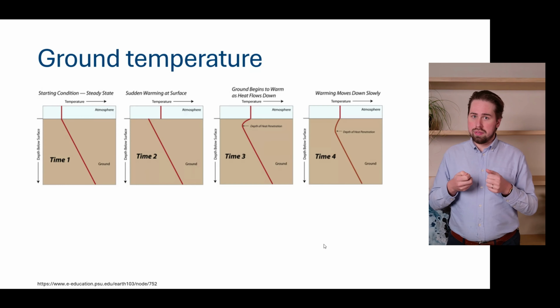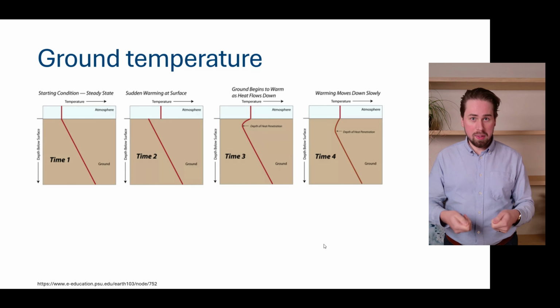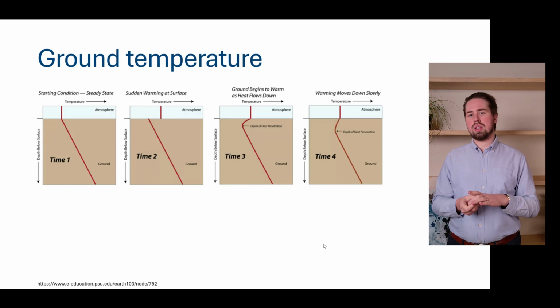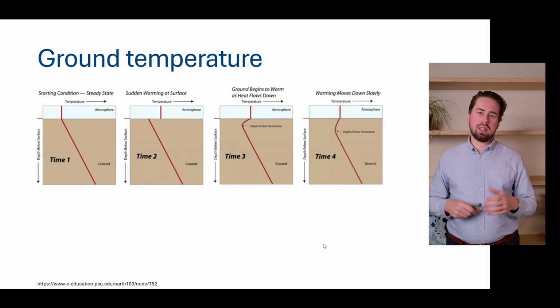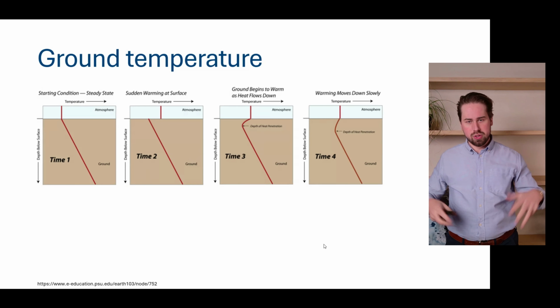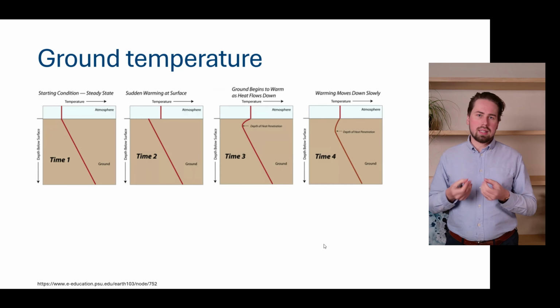So there is, especially in older cities, this problem of this temperature bubble, where if you want to find cooler ground, you actually have to drill deeper to go to this colder ground again. This is important if you have problems with cooling or your building has a high cooling demand, because you want to stay away from this high temperature, so you want your borehole to be as cold as possible. And that's an important problem.